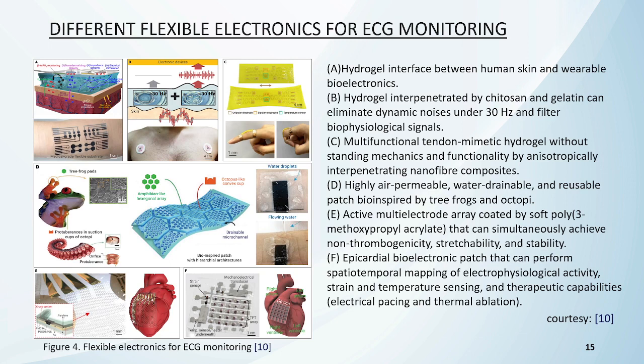These are the different flexible electrodes for ECG monitoring. Hydrogel interface between human skin and wearable bioelectronics. Hydrogel interpenetrated by chitosan and gelatin can eliminate dynamic noise under 30 Hz and filter biophysiological signals. Multifunctional tendon-mimetic hydrogel with strong mechanics and functionality by anisotropically interpenetrating nanofiber composites.